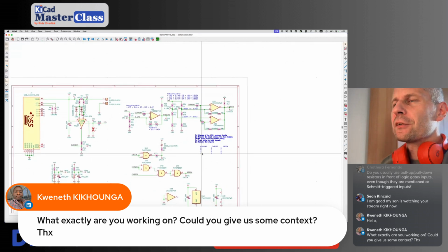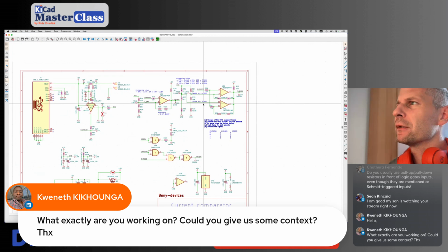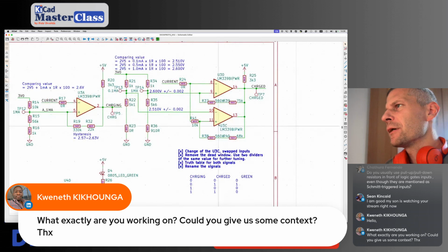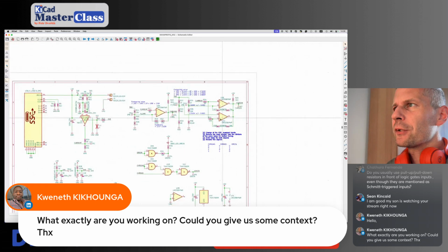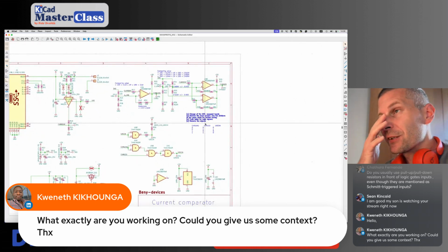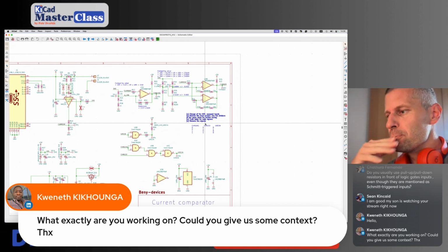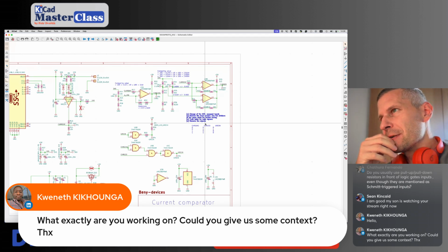I'm working on the second version of the current comparator circuit. I made some mistakes in the previous prototype version. I swapped the inputs of the window comparator and forgot to place some test points, etc. So yeah, I had to modify the circuit for the second version. The schematic was modified. Not a big change in the circuit.